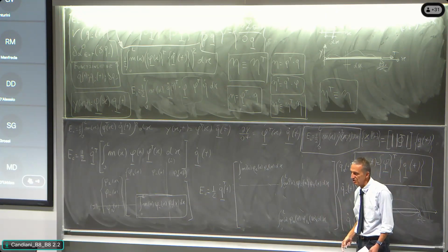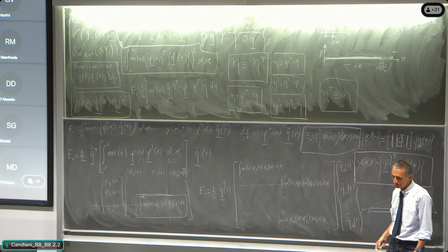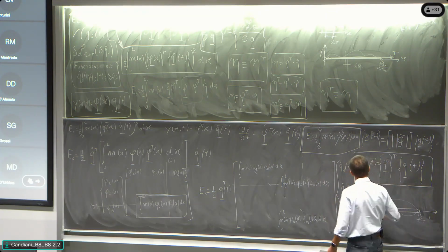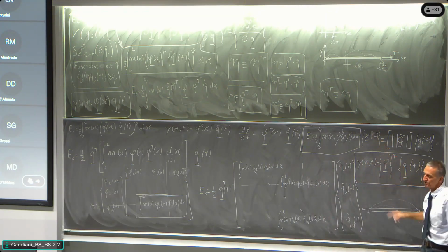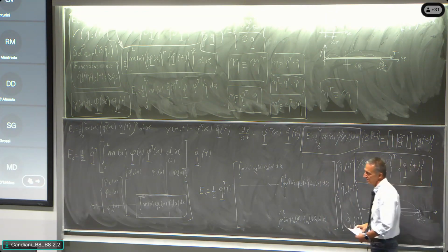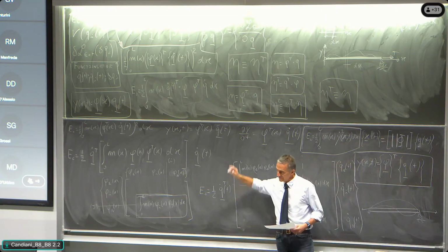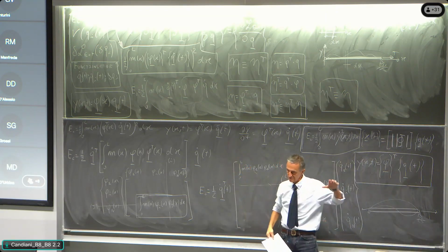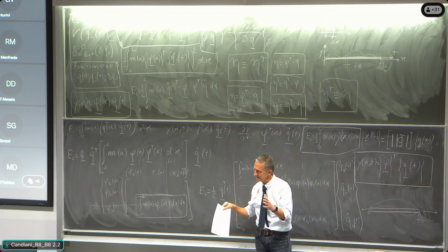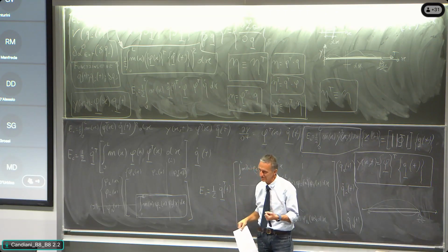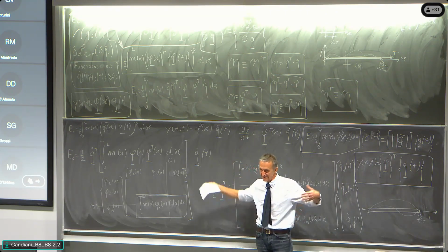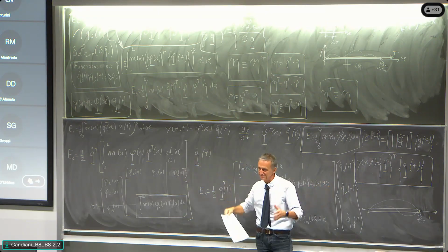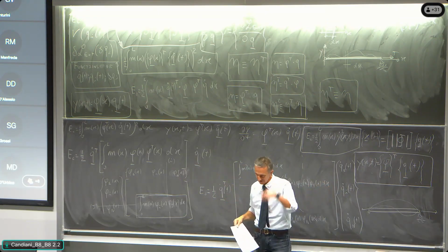What is orthogonal is not the shape. What is orthogonal is the shape weighted by the mass distribution, and it is exactly the same also in the n degree of freedom case, because we have the transformation matrix phi transposed, another transformation matrix phi, and in the middle there is the mass matrix. We cannot forget the mass matrix. When we make the transformation in principal coordinates in the n degree of freedom, we have the eigenvectors outside, but in the middle there is the mass matrix. In the middle there is also the stiffness matrix, all right?